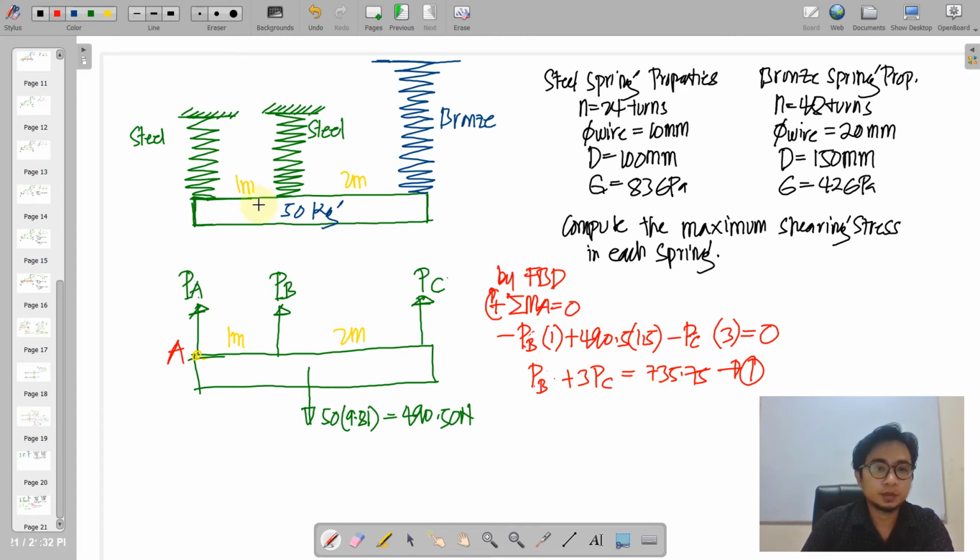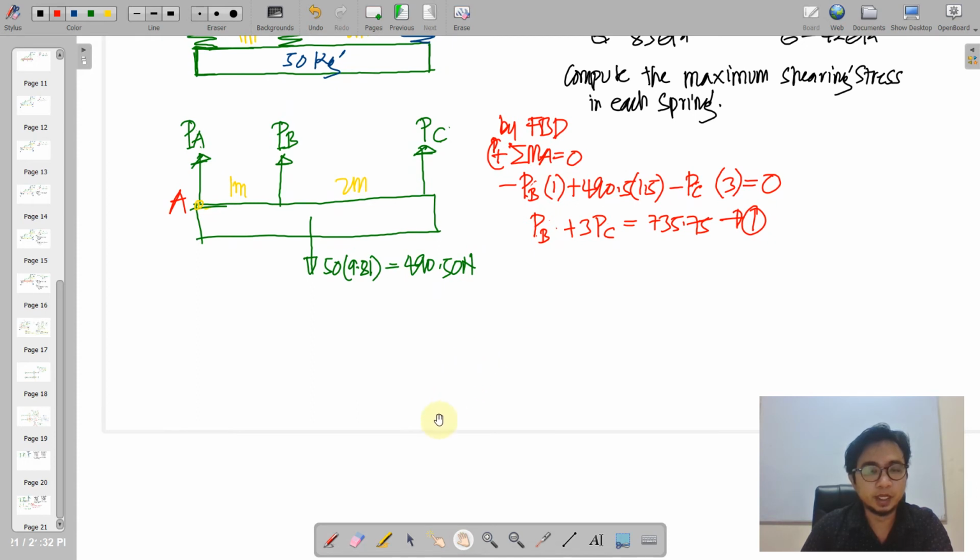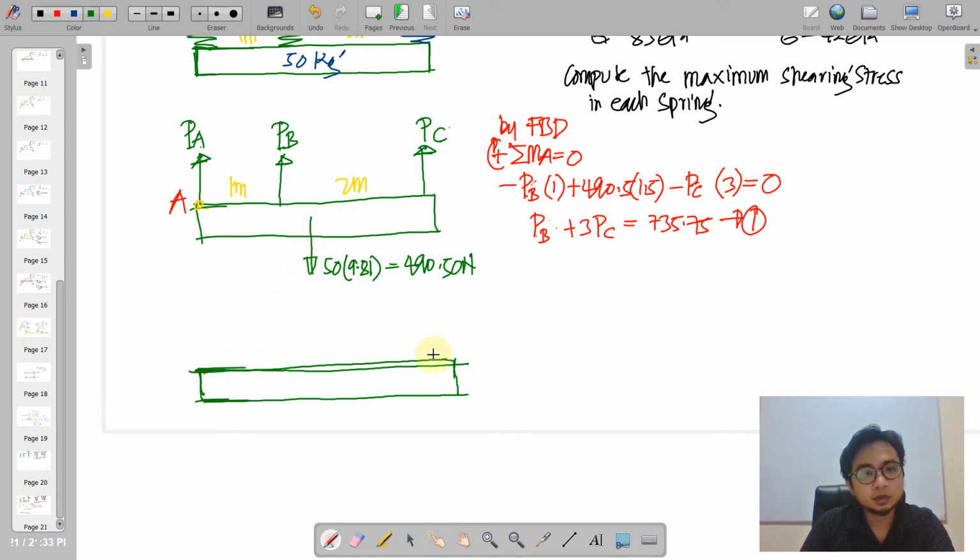Of course, from the final position of the springs, and that is by elastic deformation. So let us illustrate the platform. If we are going to pull this down, there will be a slight difference in the deformation at B and C. Remember that the deformations here are not equal because the springs are not symmetrically placed.